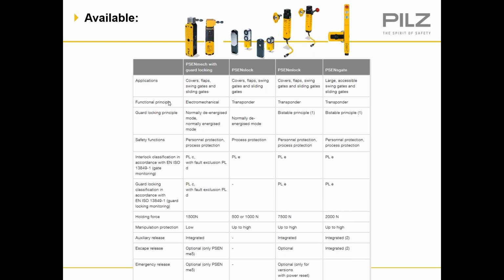The functional principle is electromechanical for the PSEN MAC, and for the remaining items they're all transponder. The guard locking principle, again for the MAC and the S-lock, is normally de-energized mode and normally energized mode, whereas to achieve the PLe for the M-lock and the S-gate we have bistable principle.